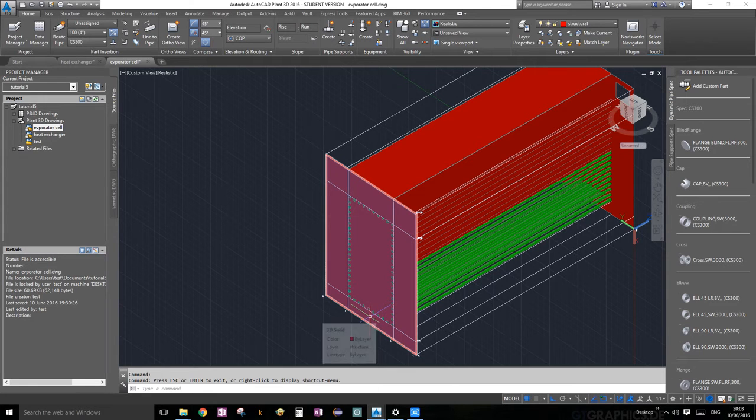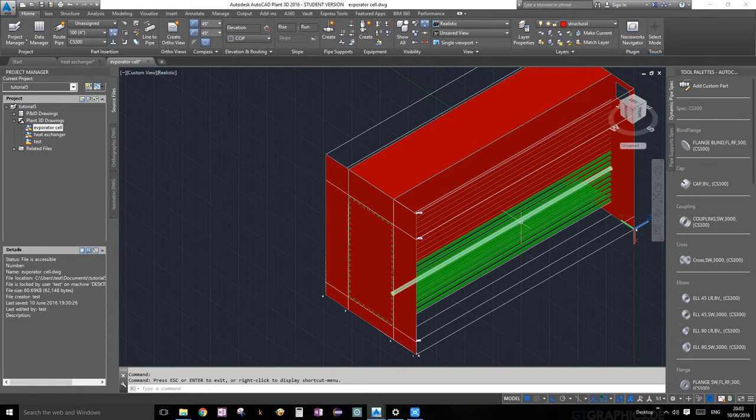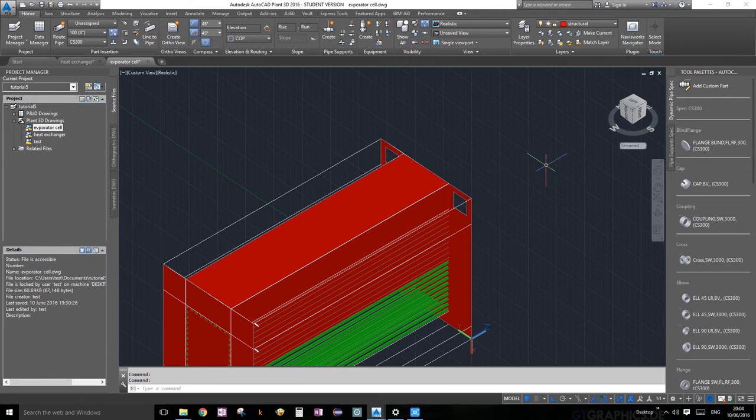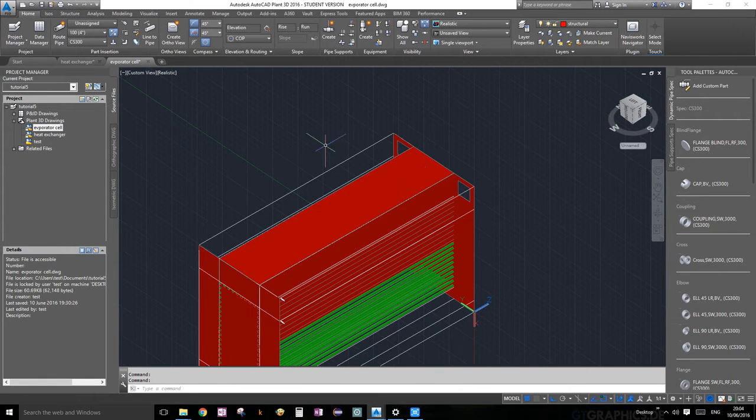And in the first cell, the vapor is going to be from the boiler, so it's going to be conditioned water. So we can't really use that distillate. That distillate is going to flow out and go some other direction we don't care about. But the vapor that the spraying water is going to create from the top is going to come through here and go to the demister, which we put so it's actually cordoning off this whole area. So none of the vapor with mist will be able to get through there. The vapor comes through this little hole here and goes to the next cell. So let's go ahead and add our demisters first.